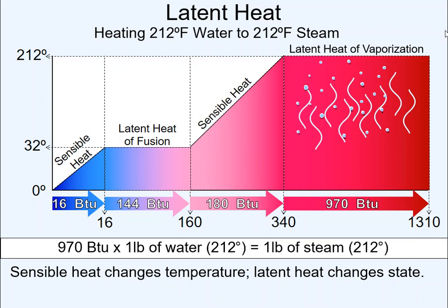So when I go from, let's say I had this at 100% vapor, I was all the way over here on the right hand side, and then I cooled it down. Well, what happens when I cool down a vapor? What happens to the air in the room if it's got water vapor in it and it attaches to that pop can? It's going to get colder, right? And once it gets to its saturation point, which is essentially its boiling point, only going the other direction, it's going to start to saturate. It's going to start to turn wet. It's going to start to condense.